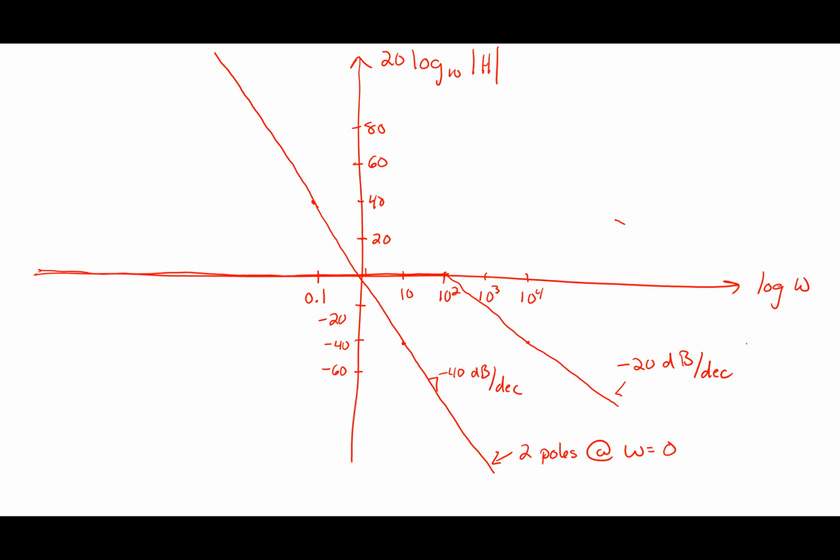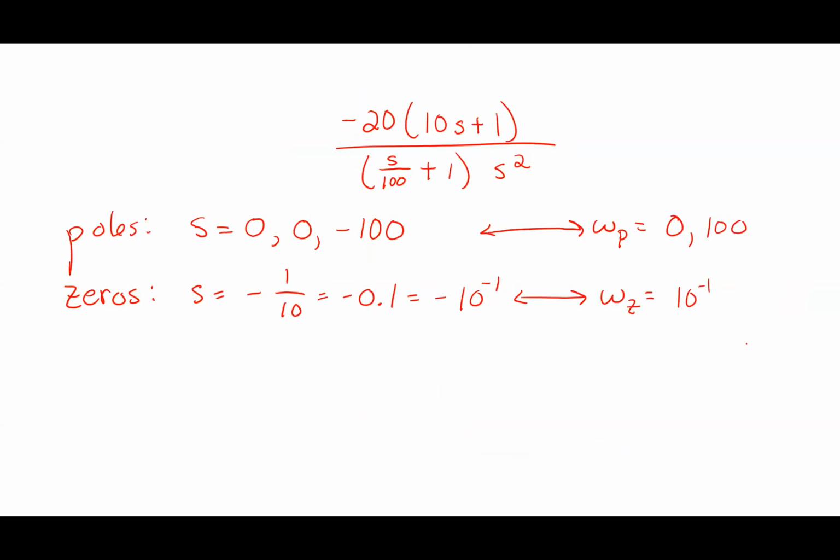That was pulled at 0. That's right. But you said it was like that before 0 and then it changed. Yeah, so where's 0? At omega equal to 0. Where's omega equal to 0? On the log scale, omega equal to 0 is at -infinity. So it's way, way off there. If I got to omega equal to 0, because these guys are on the bottom, the magnitude would have been infinity. Okay. Right.